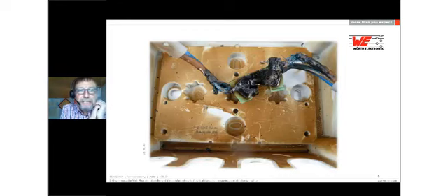The first picture you can see here is not so nice, but this was reality. This is a real application from a customer here in Germany, not a small one, it was a big customer. This is a wire-to-wire connection with a terminal block with a 5.08 millimeter pitch, 2-pole, with a cable around AWG12. This connector was powered with 20 amps, but the connector was stored in a closed box. So the heat had no possibility to dissipate, and this was the reason why this connector really burned. In the end, we had no connection anymore, so this application was destroyed by using the wrong connector. To avoid this, I will bring you this presentation today.